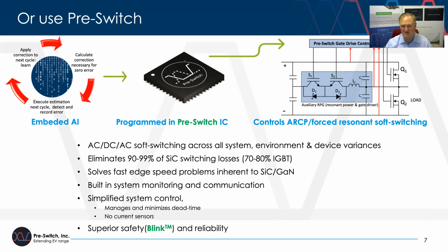Now we inherently solve the fast edge transistor problems that we talked about earlier, and we have built-in monitoring and simplified control within the chip. And we've also got a very fast DSAT protection because we're monitoring everything on a cycle-by-cycle basis.